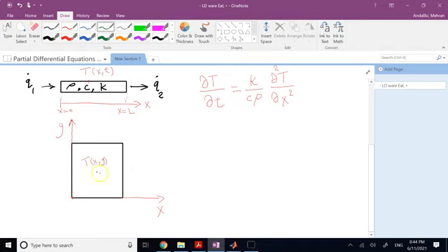And based on that, the temperature would be distributed based on, as I said, the material property of this object and based on these boundary conditions. Like which side has convection, which side is sealed, right? So for example, you might say these two sides are sealed, and then these two sides are going to have convection.